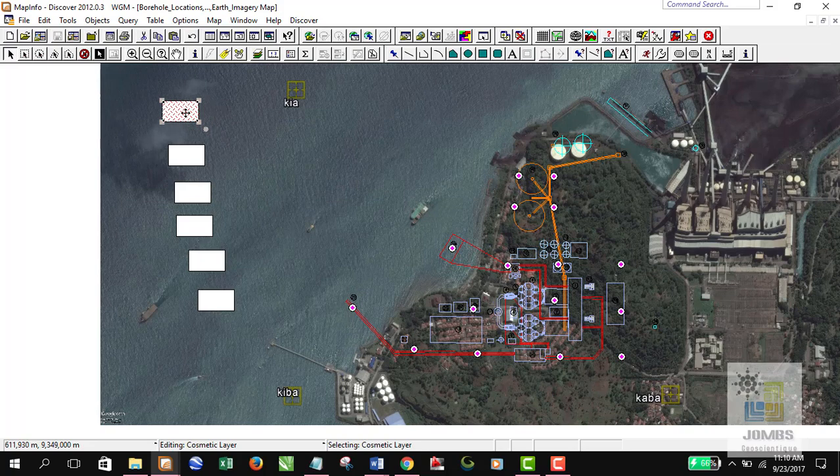So the idea of this is actually by using reference coordinates from a single object, and we would like to set the other objects with respect to our first reference. So I would like to align the following rectangles with the first top one.